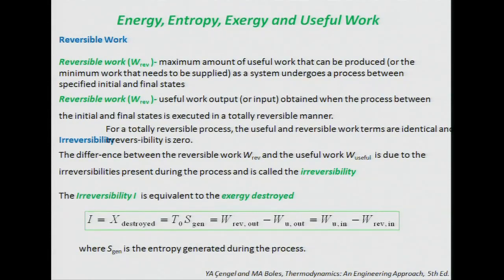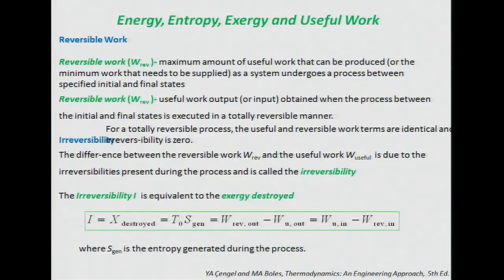So we have a certain amount of work that's available to be done by that system's energy. And theoretically, if it was a reversible process, all of it would be reversible work. But there are irreversibilities in the system, so when we subtract the actual work done from the reversible work done, that's the irreversibility that was lost. But in principle, the reversible exergy was all the stuff that we could have had in there. Okay? And we can calculate it.